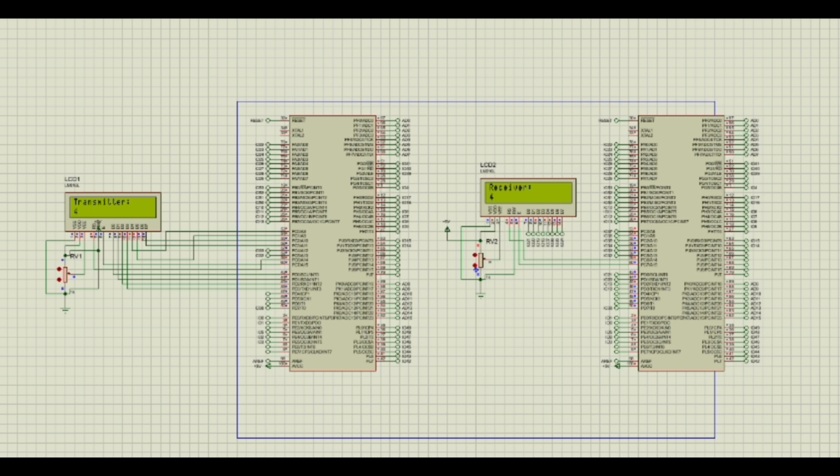So that's the wrap up of today's video. We successfully implemented UART serial communication on the ATmega2560, the chip inside the Arduino Mega. In task 1, we receive a number via UART and display it on the LCD using itoa. In the other task, a button press sends H or L over UART to control the LCD on the receiver.